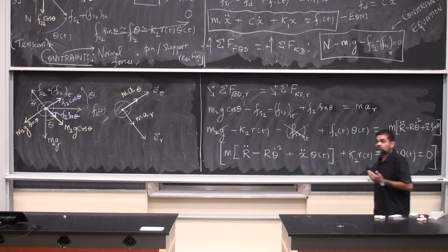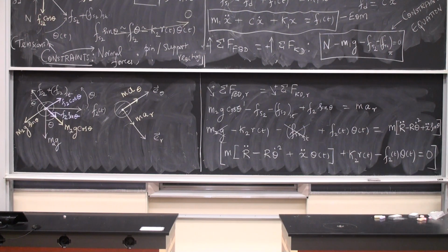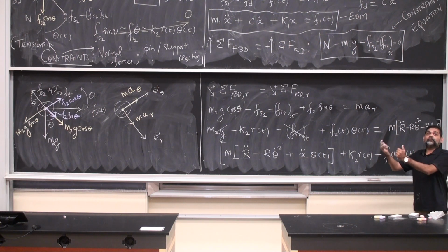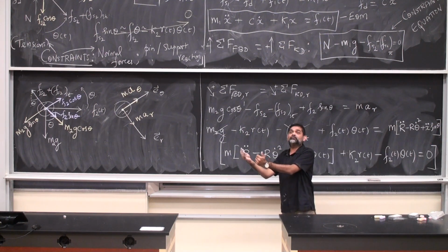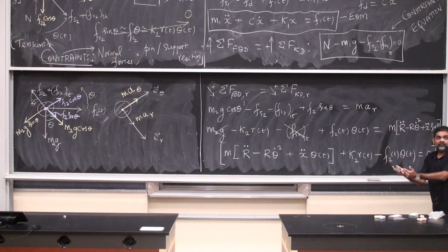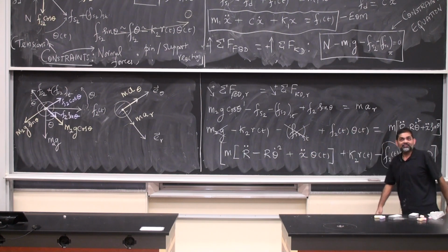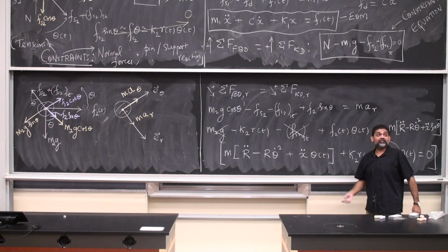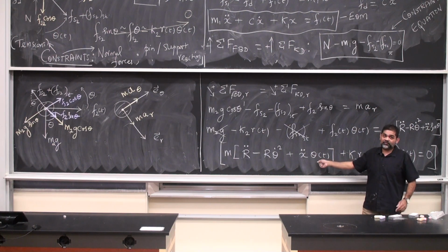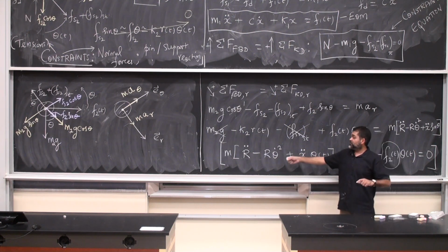This is a system that exhibits chaos. Of course, we are not going to solve it, but this is a good starting point for going into complicated things. One more time, I want to make the point, and one of you had your hands raised, and I want to answer that question. I have done one thing here. I brought F2 times theta of t onto the left-hand side of the equation, because the standard form is I write all variables that are the dependent variables and their derivatives on the left-hand side. So in the process of doing so, this guy becomes a coefficient for theta of t, which makes this a time varying system. The system is nonlinear because the dead giveaway here is theta dot square. Okay, that's nonlinear. And there is another nonlinearity here. It's x double dot times theta of t. That's another nonlinearity.